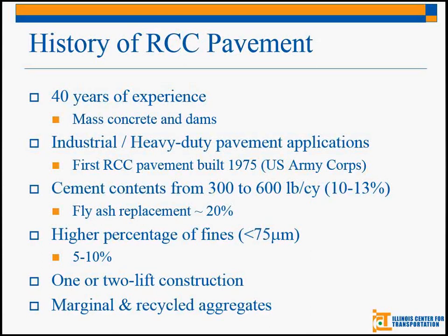it has pretty variable properties. As you can see, the 300 to 600 pounds per cubic yard of cement is pretty low. Typical paving concrete has somewhere around 600, I believe, pounds per cubic yard. So, like I said, it is a very low cement content concrete, and there have been a lot of studies on using different materials to see how they perform in RCC.